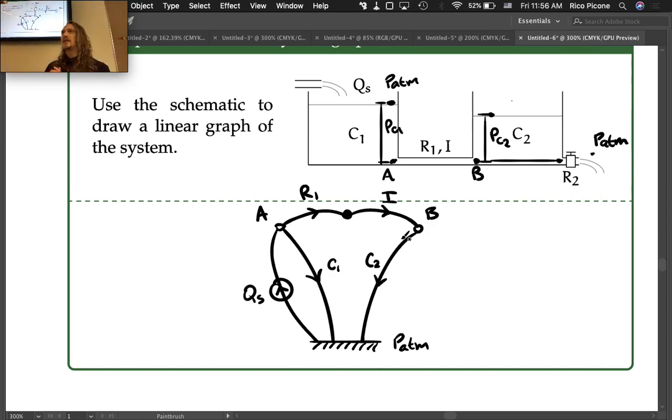And that's one thing to remember if it's not intuitive to you, that when you do pipe modeling, typically the terms should be in series if you have two, like a resistance and an inertance for a pipe. It should be in series. That tends to trip people up on exams.